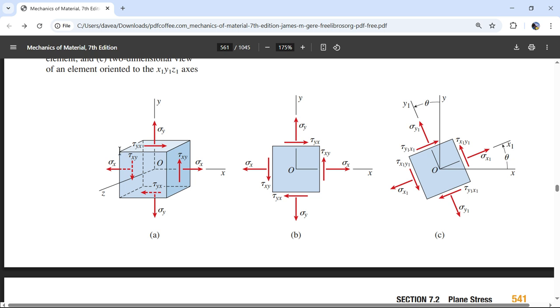This cut right here is going to give me these values. Had I come over here and made a cut this way at that same angle, that's going to give me those values. Let's see. Yeah, so if I cut here at this angle, I would get these values. And check it out: if I get one of these values in shear, I know all four shears. So I just need to do this once to get the shear.